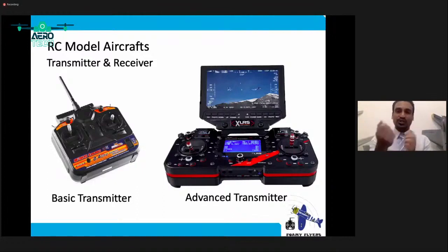But when you use a rudder input, an aircraft would normally tend to turn or dip to that particular side anyway. That's why you use something called a coordinated turn. However, if you don't have the means to buy a 4-channel or upwards transmitter, you can get away with a 3-channel transmitter.